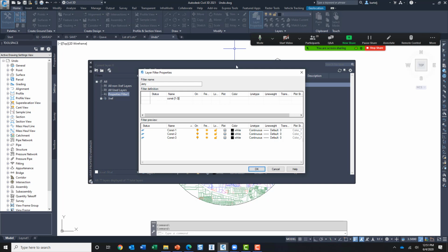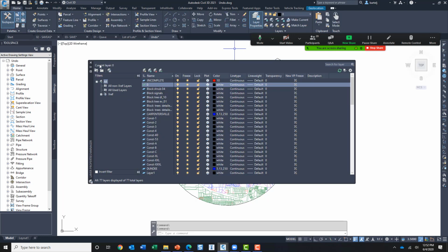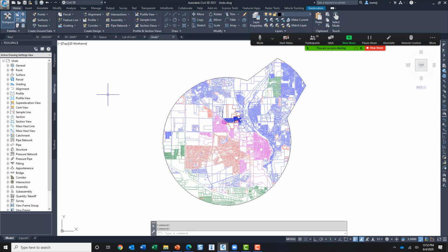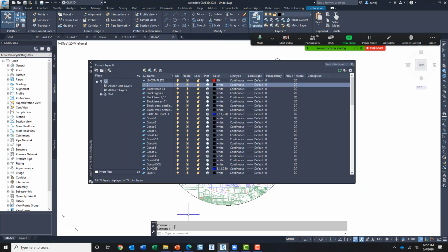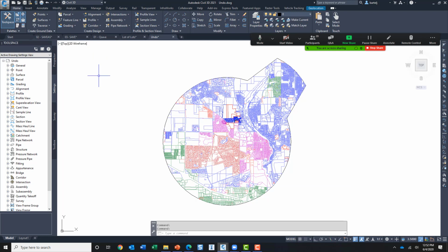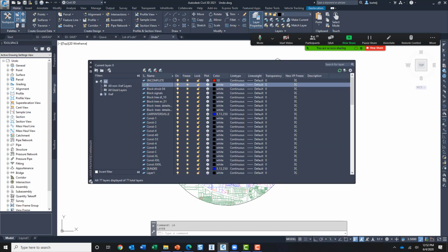They can be used for different reasons. Like I just used a hyphen in here that allowed me to find a range of values within brackets. I can also use a hyphen outside of the layers command to activate the command line version of a command. So for example, to execute layer, I clicked on this up at the top. When I do that, it's actually launching a command down here at the bottom that's being suppressed, but we'll type in LA for layer. When we hit it, we get the dialog box.